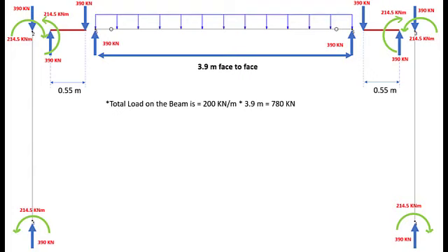In this case, however, since it is only about the rigid link between the two nodes that would solve the problem, it does not matter much which should be the master and which would be the slave node in this relationship. In the forthcoming episode on advanced topics next month, where we will discuss rigid diaphragms, we will show the importance of the precision of the definition of the master node and the slave node. Anyways, let us get back to our STAAD model.